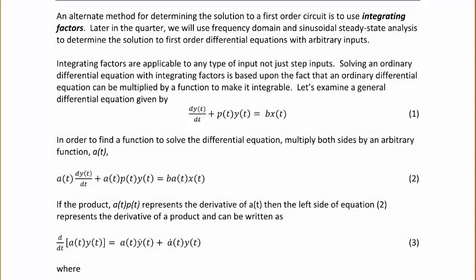An alternate method for determining the solution to a first order circuit is to use integrating factors. Later in this quarter, we will use frequency domain and sinusoidal steady state analysis, or Laplace transforms, to determine the solution to first order differential equations with arbitrary inputs. Integrating factors are used when you have any type of input, not just step inputs. So far, everything we've discussed is only applicable to step inputs. Solving an ordinary differential equation with integrating factors is based upon the fact that an ordinary differential equation can be multiplied by a function to make it integrable.